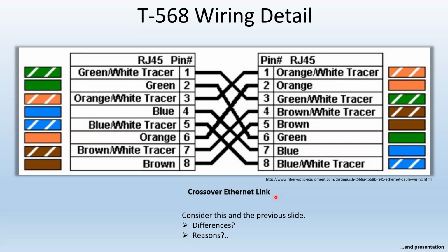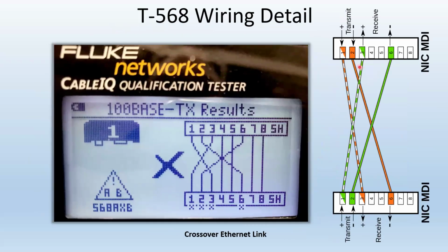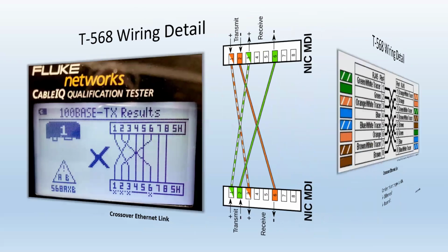Up to Cat5e, only two pairs are being used, which is the green and the orange. So if you want to make a crossover cable, you just have to cross the oranges and greens and leave the other ones intact. You're still terminating them when they're there, but all you have to cross is the transmit and receive, because only two pairs are being used up to Cat5e.